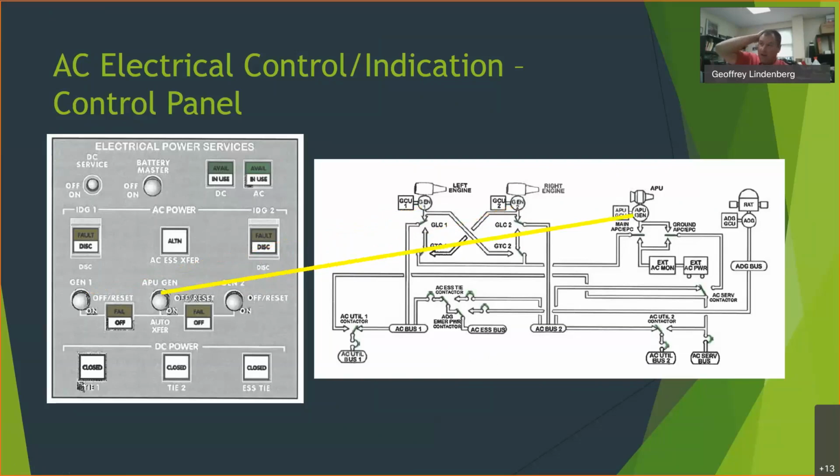Again, you turn this on, it energizes the field coils, and now the APU generator is going to run. Okay. And then these generator contactors, you can see the things that move normally are going to be automatic. So if the APU is running, they'll configure to get power from the APU, come down. Let's go back a little bit. If just the APU is running, you saw in our early example, power is going to come from the APU onto this line right here.